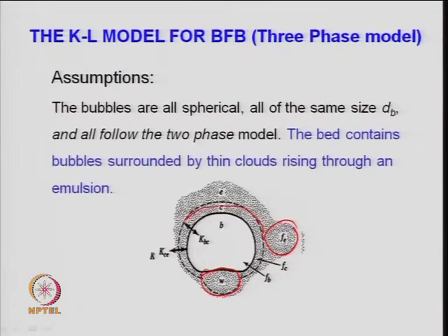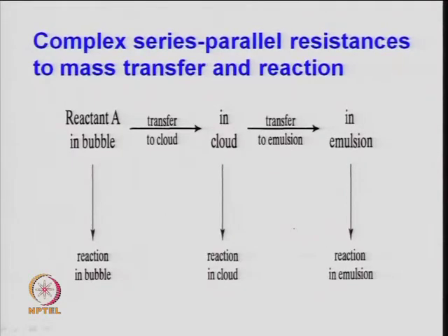Same thing, this is the cloud phase. So, mass of the solid in cloud phase divided by the mass of the bed, and this is the bubble phase. So, definitely the concentration of solid in the bubble phase will be very low. So, chemical reaction in the bubble phase is low, right. So, the reaction is in the bubble phase, the reaction is in the cloud and wake phase, and the reaction is in the emulsion phase, but the degree of contribution is different. So, this is a very complex series parallel resistance because of all this mass transfer and chemical reaction.